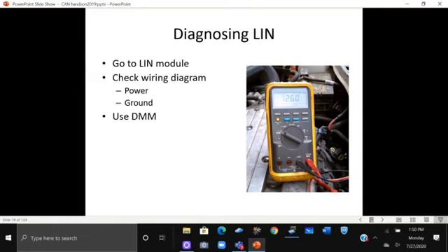When we turn it on, remember, in my example, the body control module tells the LIN, or tells the fuel pump module through the LIN that you have to turn on. And all it does is it supplies power and or ground. So if there's power applied to the connector all the time, it applies to ground. If there's a ground all the time, it connects power. And there are some brand new cars that disconnect and reconnect both wires, both power and ground.